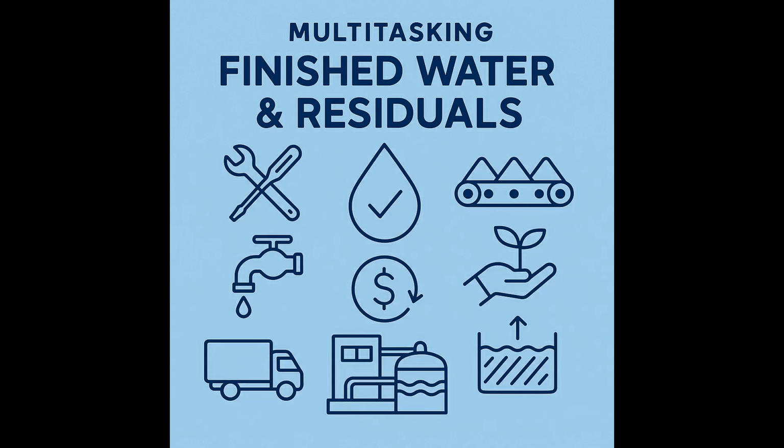Exactly. The dewatering technology is core. This is the step that turns liquid sludge into a manageable, crumbly cake, usually aiming for 15–30% solids. The main choices, as we'll discuss, are usually belt filter presses, centrifuges, or screw presses. Each has different upfront capital costs, energy demands, labor needs, maintenance requirements, and they achieve different levels of final dryness,